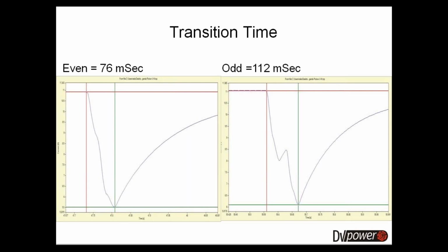What it means in real terms for the operator of the tap changer is that every extra millisecond that resistors spend in the circuit, they are exposed to more heat. And more heat means that more gases can become produced in the oil compartment, and that the parts itself have more risk of aging and more risk of damage. So you want the transition time on every tap changer to be as short as possible.